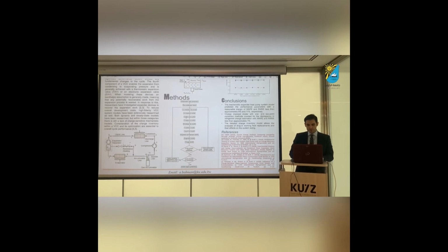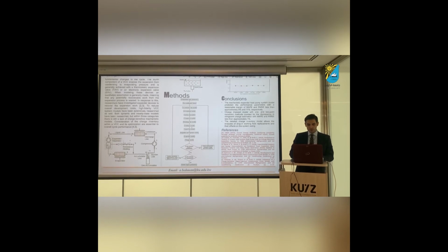So after the discharge model, the information goes to the condenser model, liquid line model, expander model. So this is basically the detailed model which we worked on, then the evaporator model, and finally the charge model. And it's checked for the saturation temperature. If it's satisfied, it converges. Otherwise, the model keeps iterating.